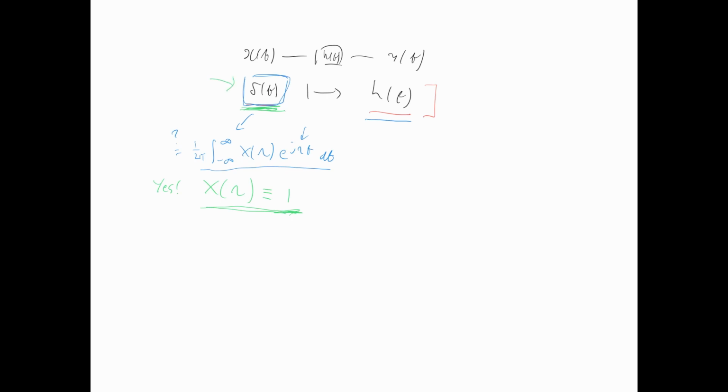This is why putting in the delta function is a good way of understanding the channel behavior. If we had forgotten to include some frequency components, then we would never know how the system responded to inputs at those frequencies, and therefore we couldn't work out how the system responded to arbitrary inputs. Any input that contained a frequency which we had not yet probed, we could not determine what the output would be.